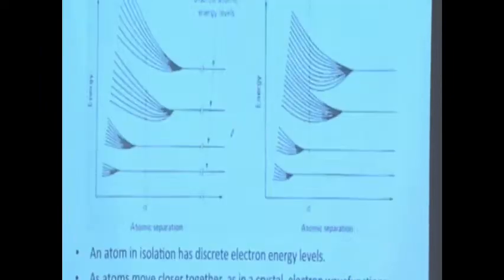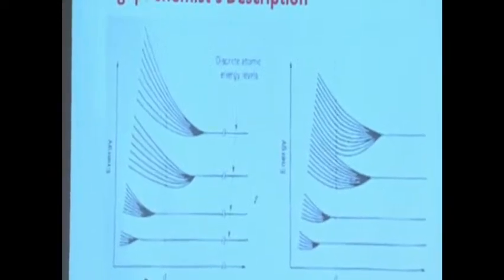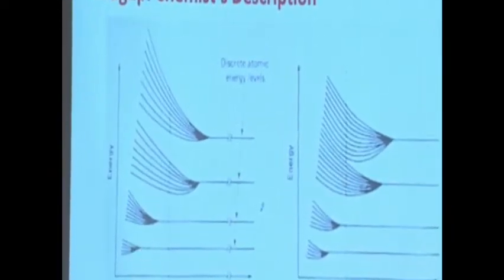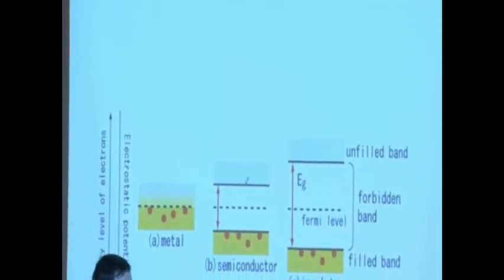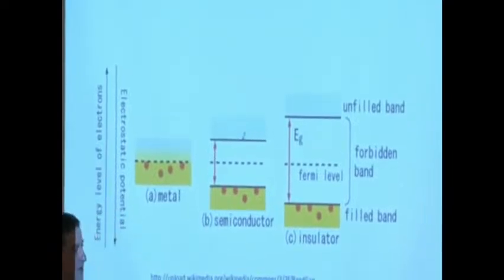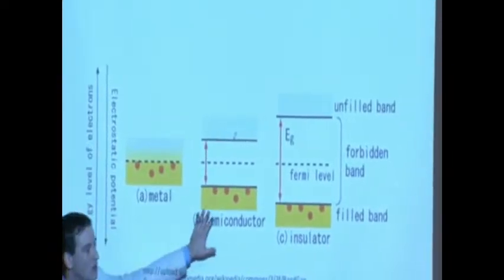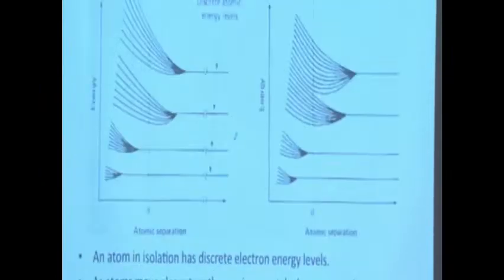This diagram here can get kind of confusing when you look at the abscissa, essentially the x-axis, because you're thinking in terms of real space. Well, it is real space, but you're bringing atoms together. It's really meant to be a phenomenological tool to describe how band gaps form. This diagram over here, we're now starting to get into the engineering diagrams that can help explain how solar cells work. And from here on out, we'll be abandoning that chemist's diagram and simply using this one, because we assume that we're not applying a significant strain to our semiconductor material.